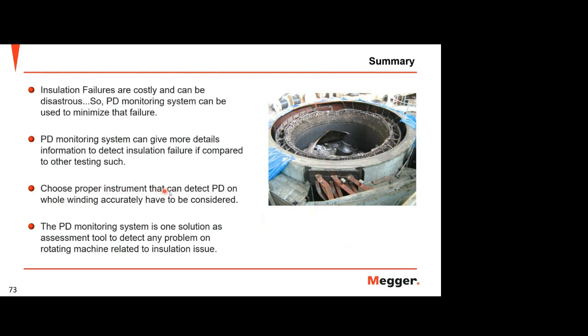Choose a proper instrument that can detect PD on the winding accurately, because remember, different frequency ranges also affect the measurement. High frequency range will lose some information from the whole winding. So you can decide when you consider online monitoring.